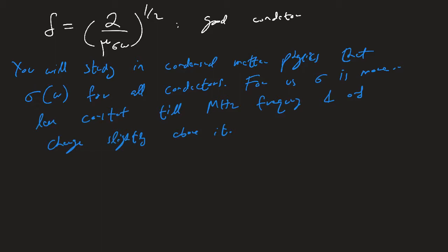Anyways, so most metals are good conductors up to very high frequencies, and let's see what the skin depth is for different frequencies. So at about f equal to 50 hertz, so if you have an electromagnetic plane wave of frequency 50 hertz, so omega would be 100 pi. So the skin depth is approximately 1 centimeter.